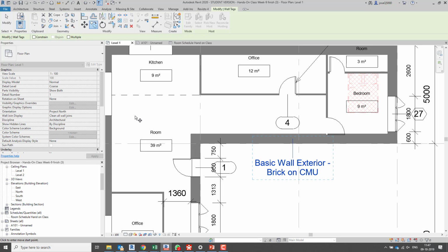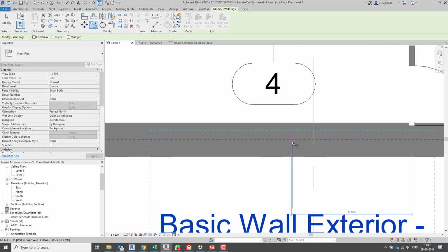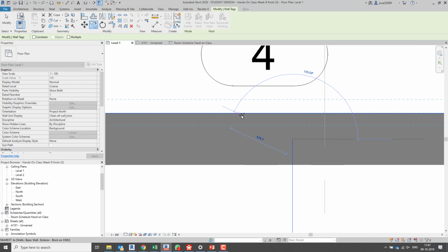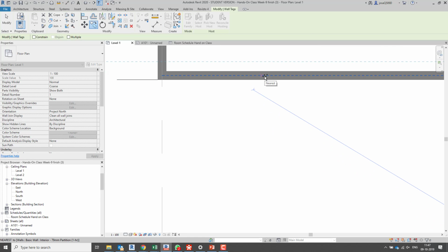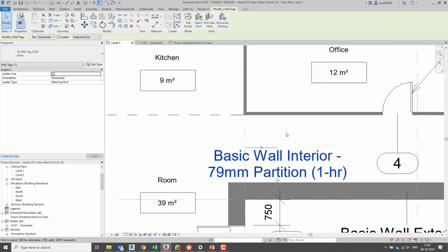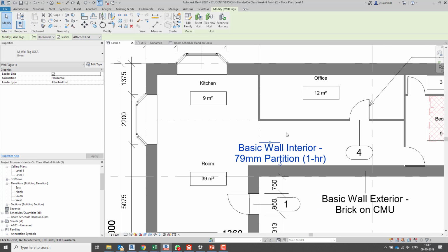Guys, click to enter move start point. So the same as in AutoCAD, it's asking me where I want to start the copy from. I want to start from the insertion point. Then I'll just move the insertion point of the copied tag to the center of this wall. Because the insertion point is what reports, it then reads another wall and another parameter.